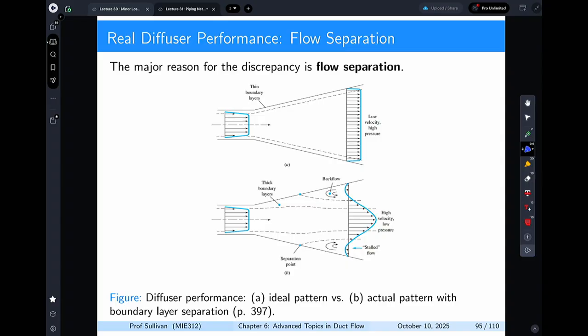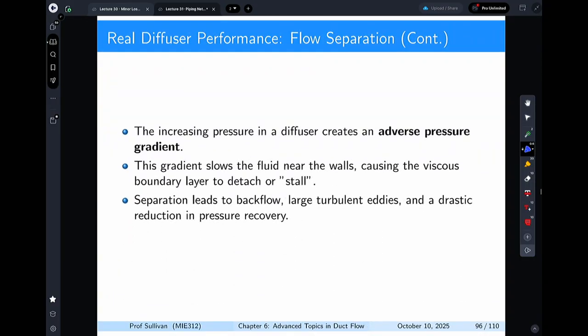So you have a flow that comes out, and ideally it will behave like it does on the top. It spreads out nicely, and it comes to the very top of that, and it will proceed and move gently out. The reality is that in most cases, high momentum fluid will continue. It will cause a secondary flow, and there's a stalled flow that occurs, and that reversing causes a pressure drop. And that's part associated with an adverse pressure gradient where delta P over X, where X is the downstream distance, is greater than 0.